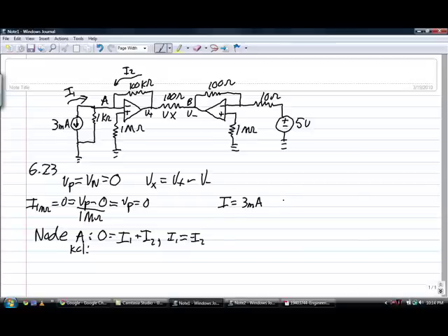And we know that our R sub Thevenin is equal to 1 kilo ohm. So using Ohm's law, we know that the voltage would equal 3 volts. However, the arrow's pointing in the opposite direction of our current, so why don't we make this a negative, and then we can reverse it.